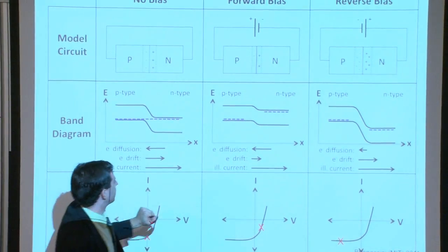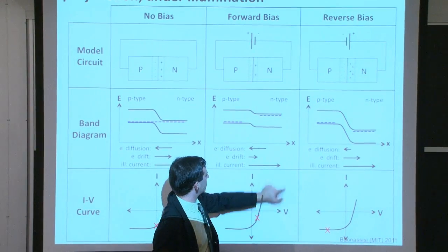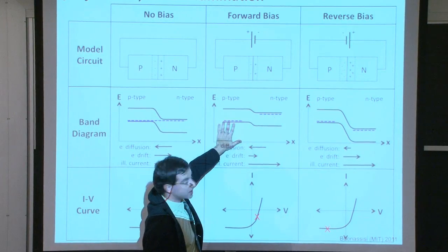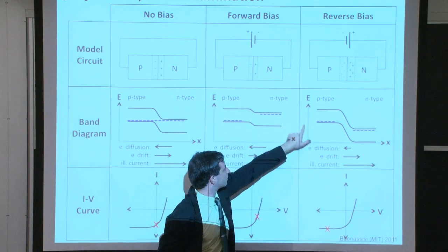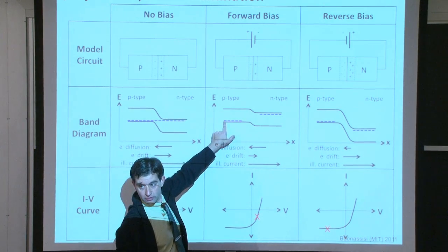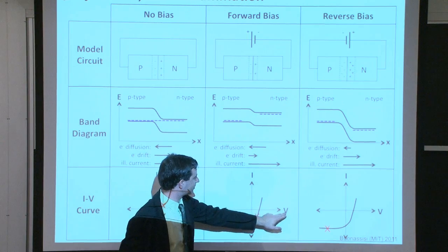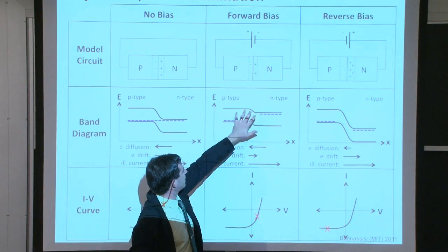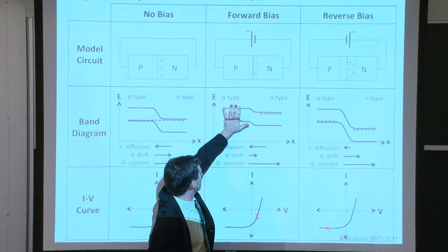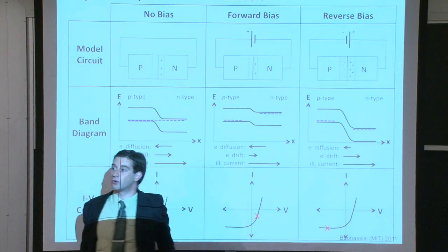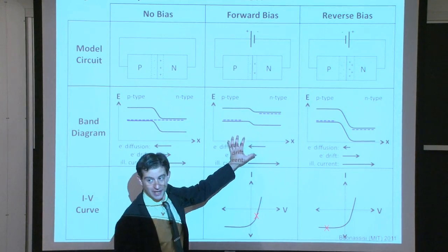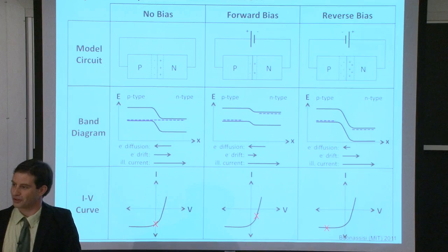Why? Well, first off, the voltage is such that we can power an external load. We have charge separation. The electrons are accumulated over here, and they have higher potential than they do on the other side, which means that there is an incentive for them to go through the external circuit, deposit their power across that external load to get back to this other side where their potential is lower, right? So the voltage is favorable. And the current is also favorable, because now we have light coming in, and this generation current is creating carriers here in the p-type that can then be driven toward the n-type because of the built-in field. So the conditions are just right under illuminated forward bias conditions to drive power through our external load.